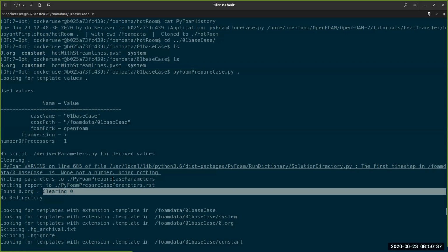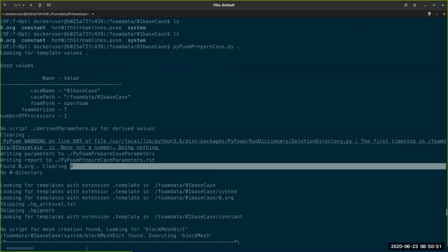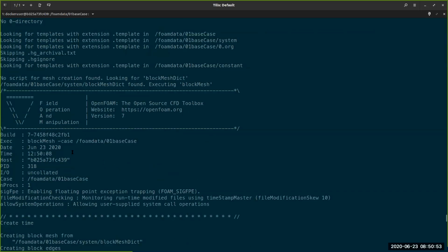And if you hand edited these files yourself, then the stuff is gone. So I think it's better to start off with a directory that OpenFOAM usually doesn't touch, copy it over to 0, and then do things like running blockMesh.